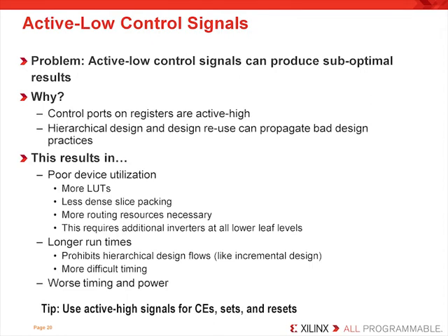And as I mentioned earlier, active low control signals are simply not recommended. This is because the flip-flops do not have local inversion available, and instead inversion requires a LUT input. And keep in mind that designing with active low control signals is an older design practice, so always check what is available in your silicon before designing in an inappropriate signal.